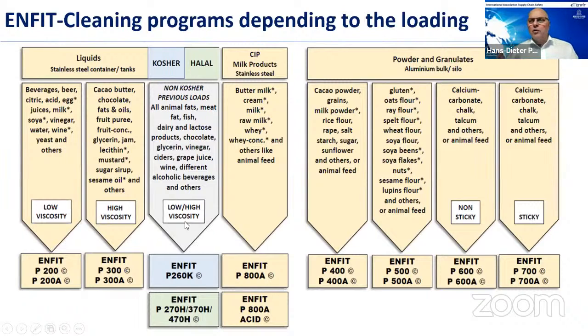That means which kinds are not allowed, but when they are allowed or transported, which kind of real cleaning procedure should be used. And here you will find numbers. Those are also cleaning codes, but behind each code is the clear process. The process means disassembling from residues, preparation of the tanker, a main pre-wash, a main wash, a rinsing, a drying, assembling of the attached parts, a clean test with its result, and then producing the document. And that is the total cleaning time that we have developed, and these cleaning processes.